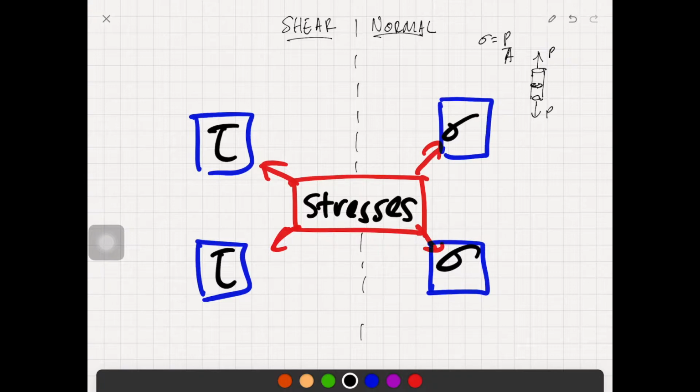And the second one is, I'll call it, the most selfish equation in solid mechanics. We have sigma equivalent to negative My over I for bending stress. This is normal stress, this is bending, and here M is the moment.